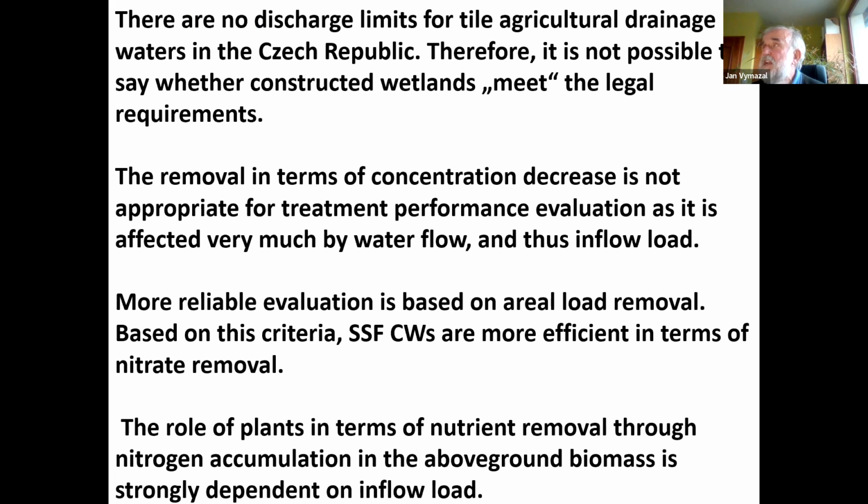It's very difficult to say, at least under Czech conditions, whether they meet requirements, because there are no legal limits on discharge of agricultural drainage waters. Therefore, it's difficult to say if they meet the requirements. But the results show that the wetlands are able to remove relatively high amounts of nitrogen and phosphorus. And our results more or less confirm what has been reported in the literature.